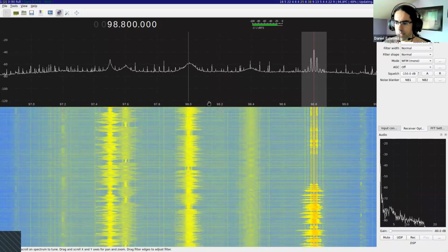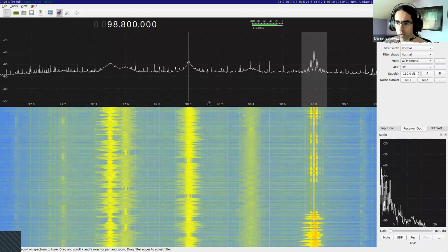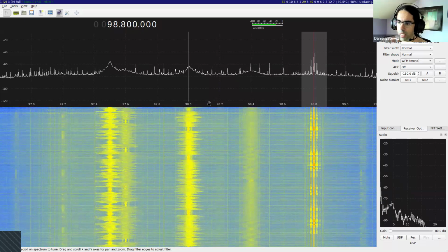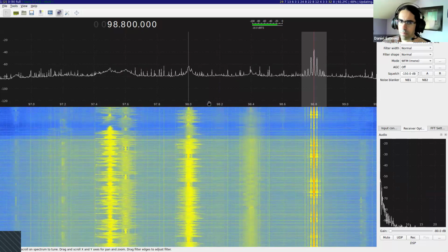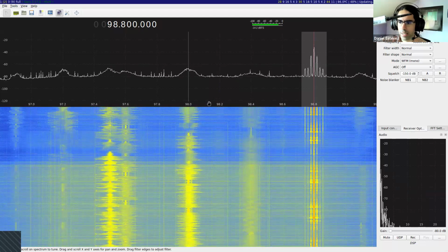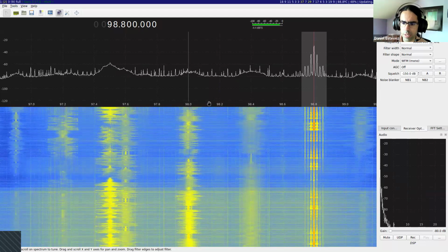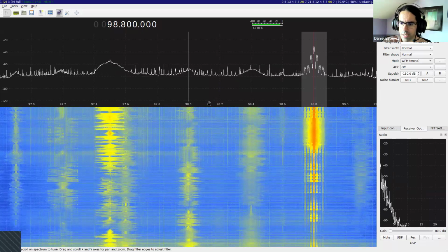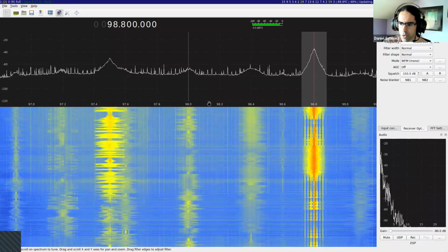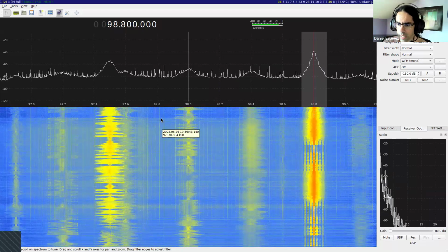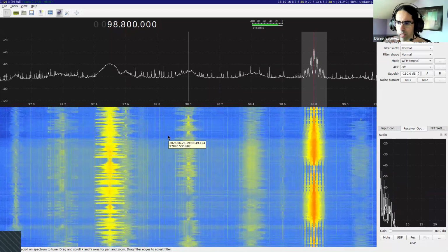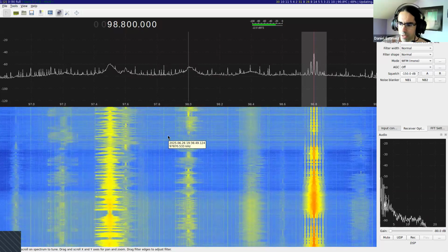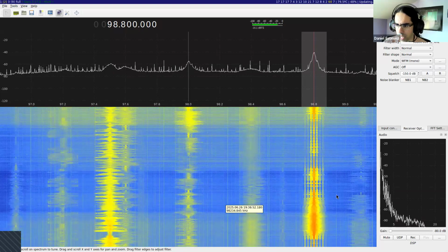All of those devices radiate radio frequency signals unintentionally because of how the electronics work. And something I can demonstrate is I've picked it up with my hand, and if I put it, I don't know, next to the screen or something, you will see that some of the spikes change. For example, they are stronger there, and the noise floor is also changing as I'm moving the receiver. So all of that is local radio frequency interference, both the noise floor.